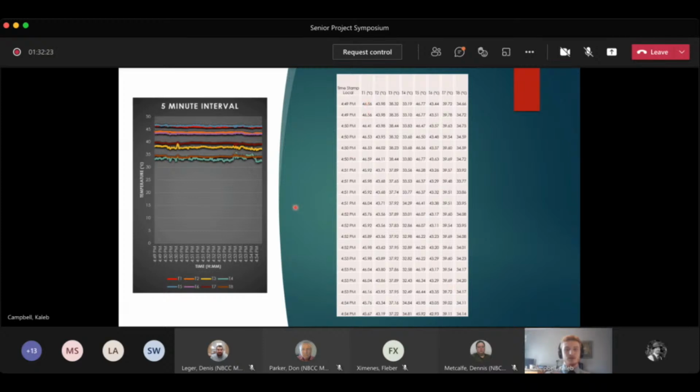So first, in order to put in the calibration, it is all done in an Excel spreadsheet. Within the Excel spreadsheet, the main voltage to temperature conversion is done, and from the voltage to temperature conversion, the calibration is then applied. As you can see here, temperature sensor 1 is at the top of the collector. The first row here is showing the aluminum screen collector, and the bottom row is showing the aluminum can collector, or aluminum cylinder collector.